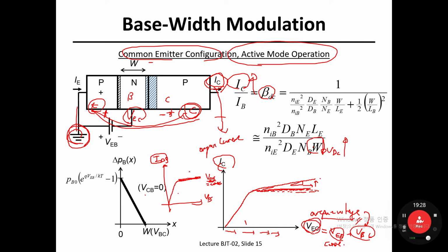However, if your physical channel length is very short, then as the output voltage VDS increases, the drain current is also increasing. So you get this experimental data point in the end. So your MOSFET is not perfectly working as an independent current source in saturation mode, which is bad news when designing your MOSFET-based amplifier.